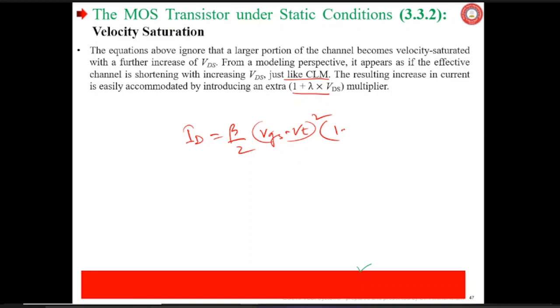Here, what we try to understand from these plots is the behavior of the NMOS transistor in the different regions, which is best understood by analyzing ID versus VDS plots, with VGS as parameter. For different VGS, like 1, 1.5, 2, and 2.5, it has been plotted. And we see that quadratic dependence is there here.